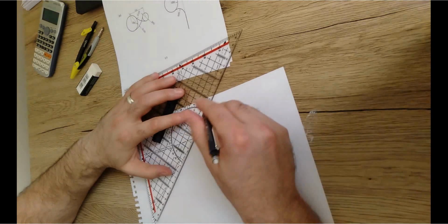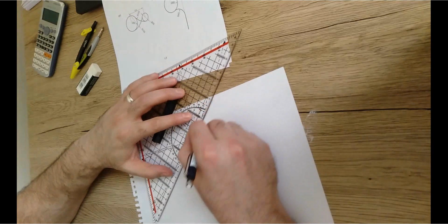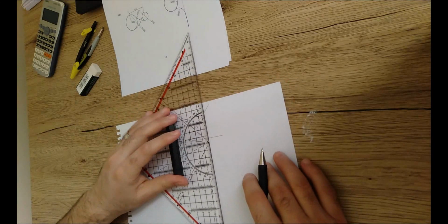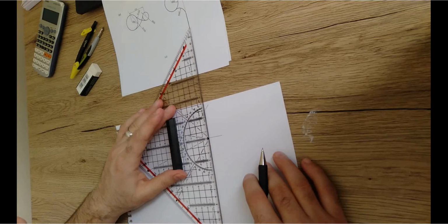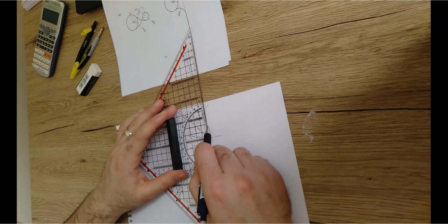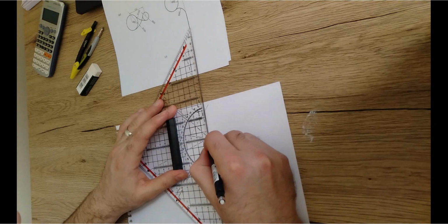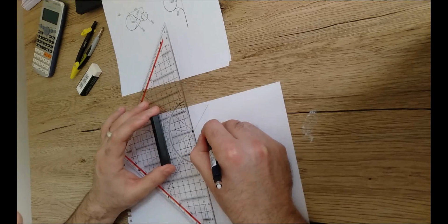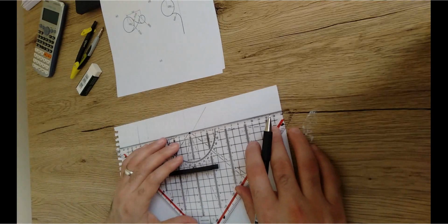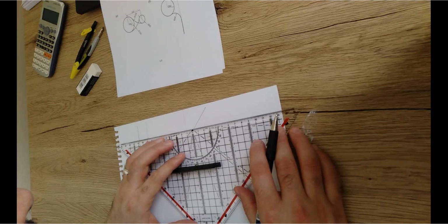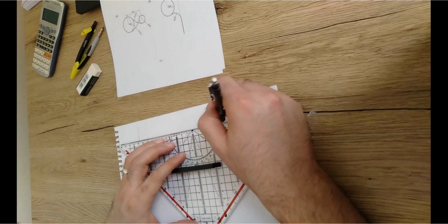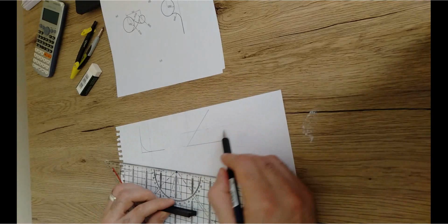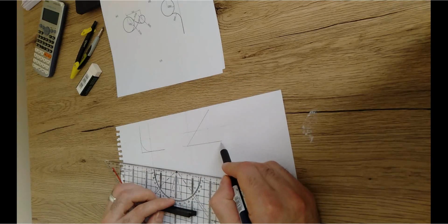And this is the second line, which is already given here, right? So what I'm gonna do is draw a very light vertical line that is barely seen. Then over this line, I'm going to measure 20 millimeters, 10 and 20. So this is the mark. Then from this point, I'm just gonna draw a line that is completely parallel to the previous line in this way. So this line here is the one that is parallel to the baseline or the original line.